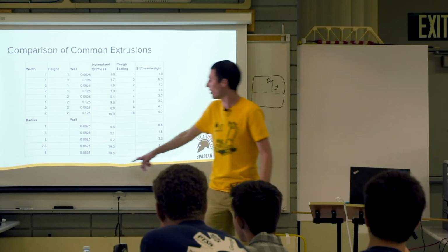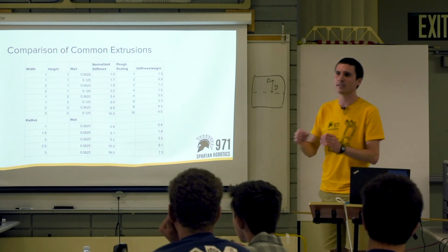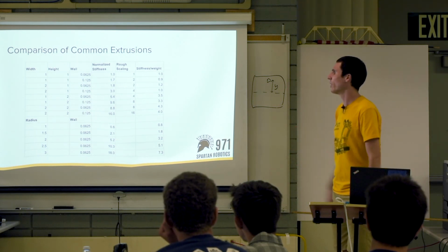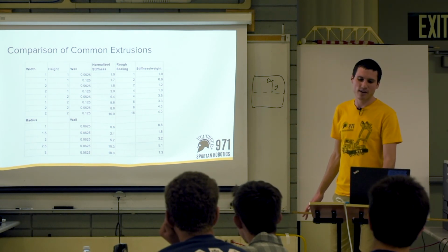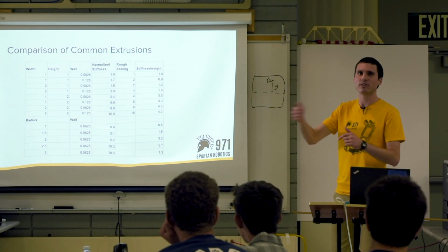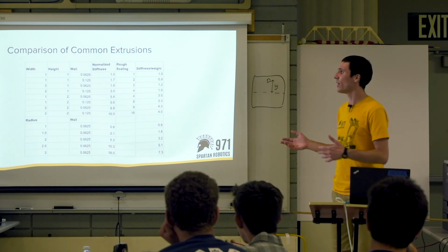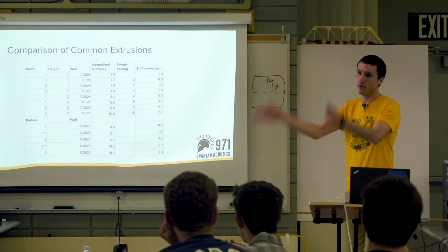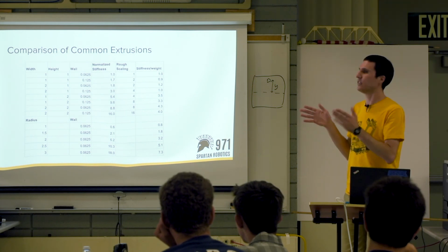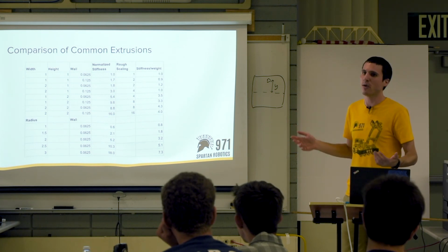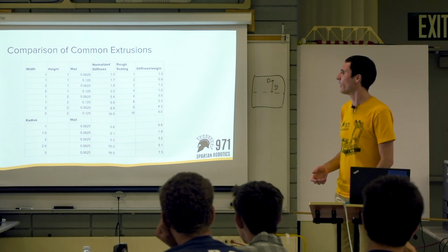You'll just notice that as you go to the larger and thinner wall tubings, you can get really stiff and really light things. So you'll notice on some robots they have big round tubes. That's one of the reasons. And I should add, the difference between round and square tubing is that round tubing has the same stiffness or strength in all of its directions, and square tubing has its strength in a specific direction. So if you know what direction the force is, like on our intake arm, we know most of the force is going up and down, we can direct our tube to be stiff in that one direction. If we don't know what the forces are, like the front of our intake, round tubes might be better there.